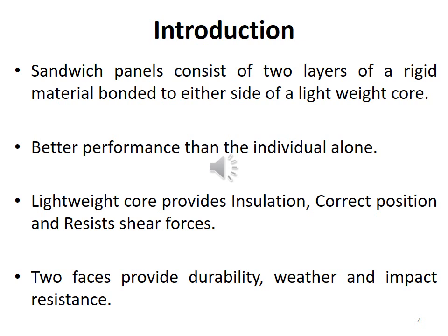So in this way we have a sandwich panel, which is actually any structure made of three layers: a low density core, that is in between two skin layers bonded to each side. The sandwich panels are used in different applications where a combination of high structural rigidity and low weight is required.